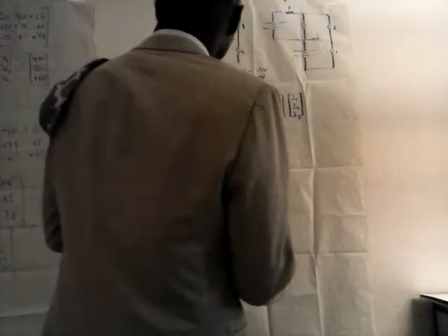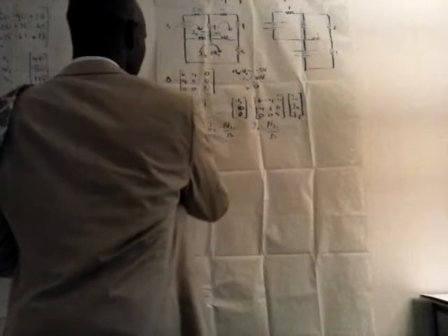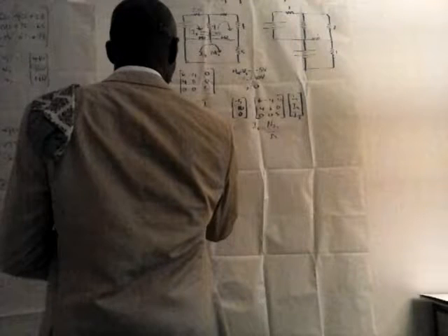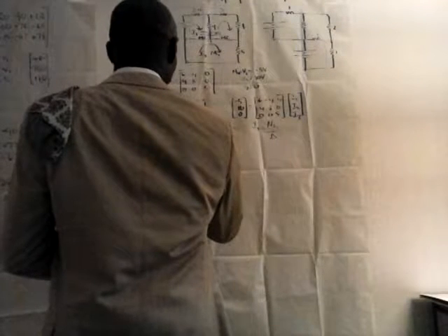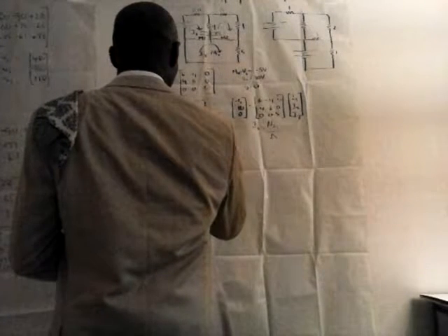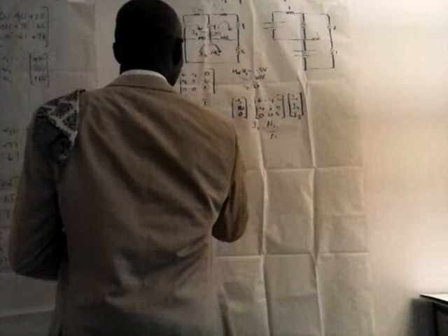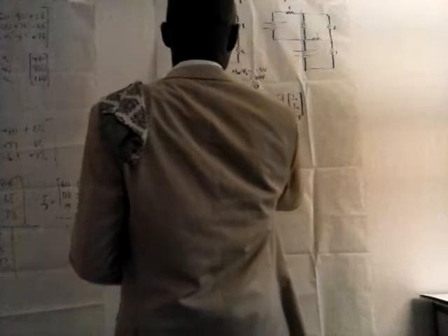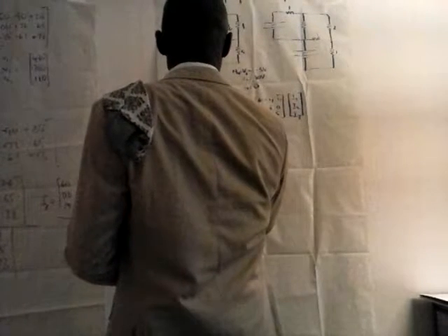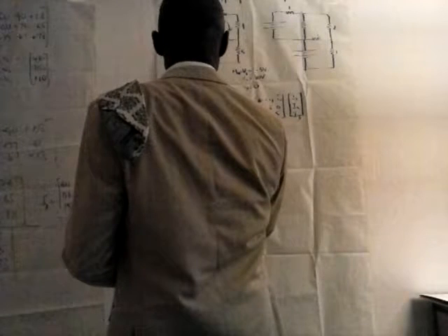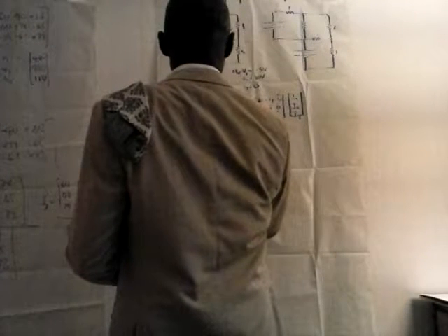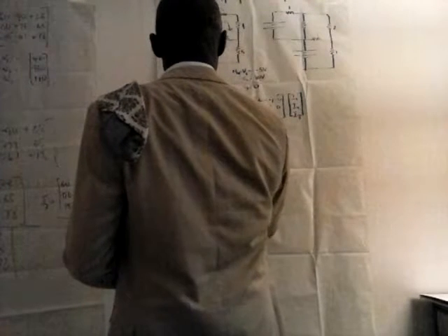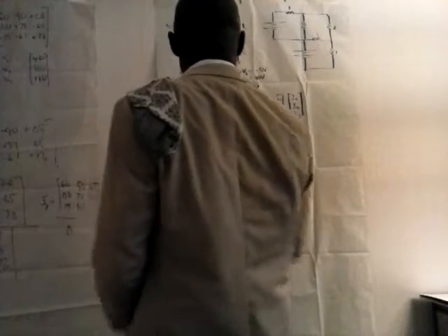So here we are now at the point to find I1, which is Ni1 over delta. We find Ni1 first, which is equal now to: replace the first column with the voltage values, so we have -5, 10 and 0, -4, 8 and 0, 0, 0, 0. That is to find Ni1, the determinant of this matrix.